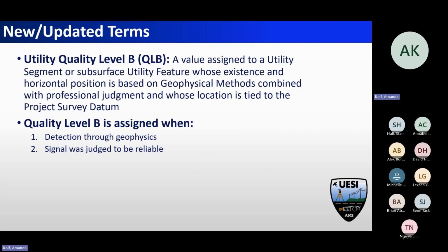because we were putting a fence in the backyard of our office, and when the guys marked it, we've got a water line and a telecom line. Well, the telecom line started meandering over toward the water line, and it meandered back. Did it really do that, or was there some kind of signal interference? Just because the guys marked it doesn't mean that's necessarily exactly where that line is.